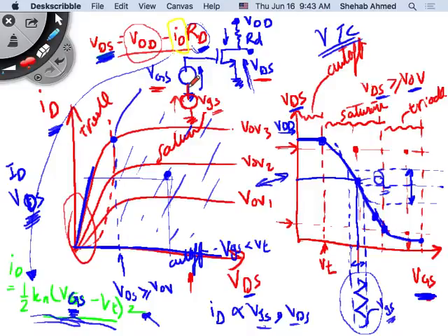So what are these doing? One is putting the device here. This is my big source, my DC source, the DC operating point analysis that we did before yesterday. And then this small one is adding a small signal here. This small signal is a voltage above and below your DC operating point.